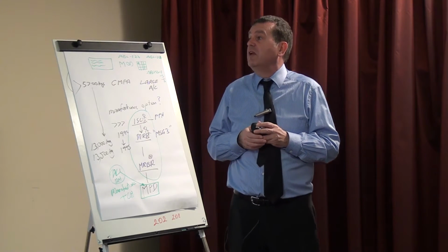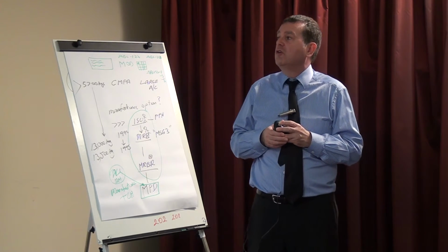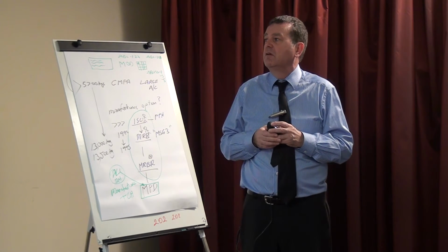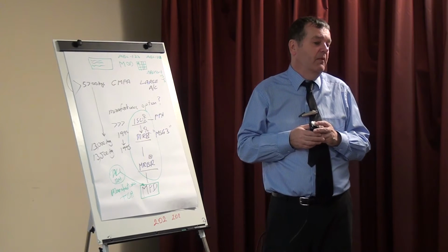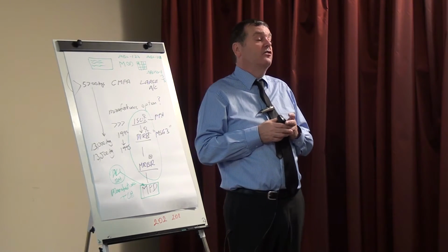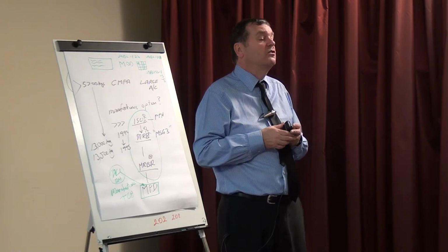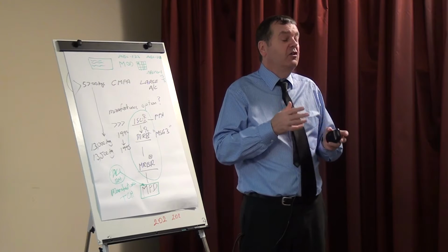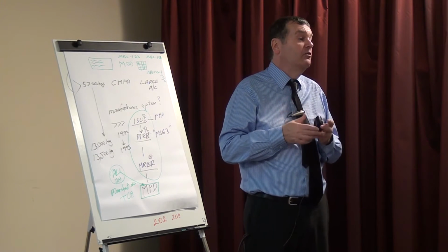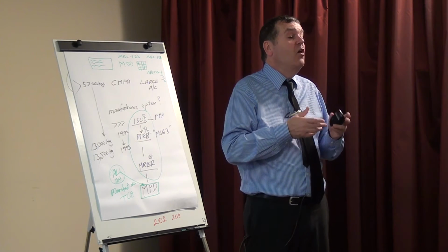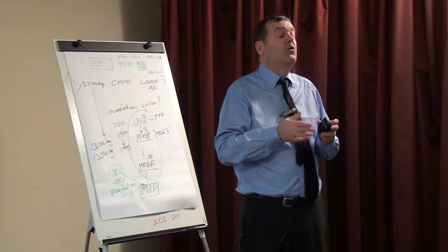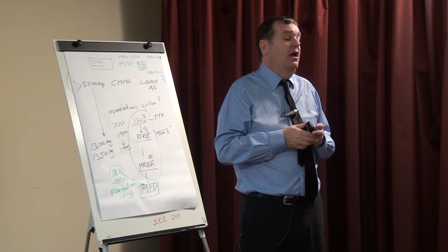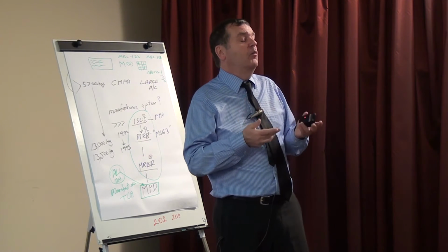Condition monitoring applies to items that have neither hard time nor on condition maintenance, and simply means the part is left to expire. So we leave it. We know one day it's going to fail and we accept it, because we can live with the consequence of the failure. Once you decide you can live with the consequence of the failure, it becomes very different. And we know for a fact that all the components are not going to fail on the same day. It doesn't work like that. So we can wait for a component to fail and we can deal with it.